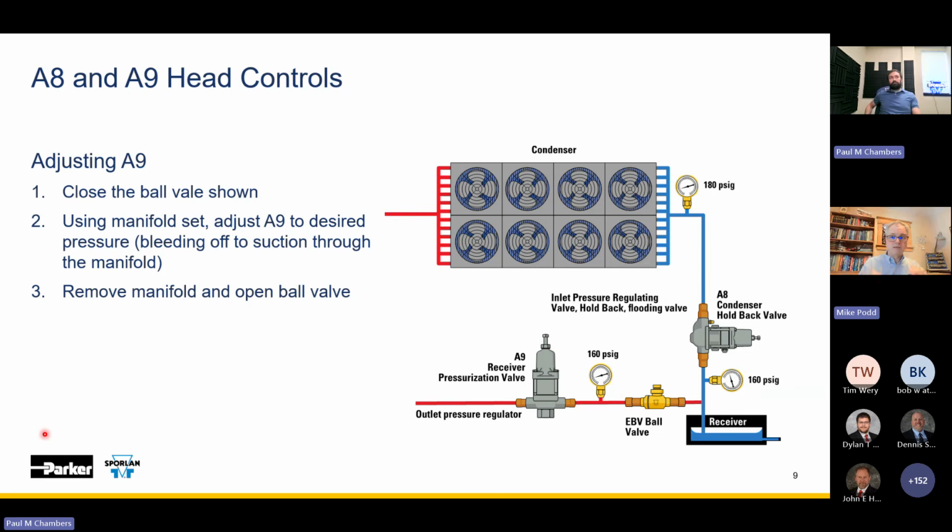Now, can you vary that speed? I'll let the condensing unit manufacturers make that determination, because they may have a strategy for varying the speed of that single fan down to a lower limit that doesn't see the abrupt changes in pressure. But it's the changes in pressure that are the concern for us. The condenser manufacturers might have another concern about the expansion and contraction of tubes on the header. But no, don't cycle a single fan. Always have at least that one fan running to keep stability in the system pressure.